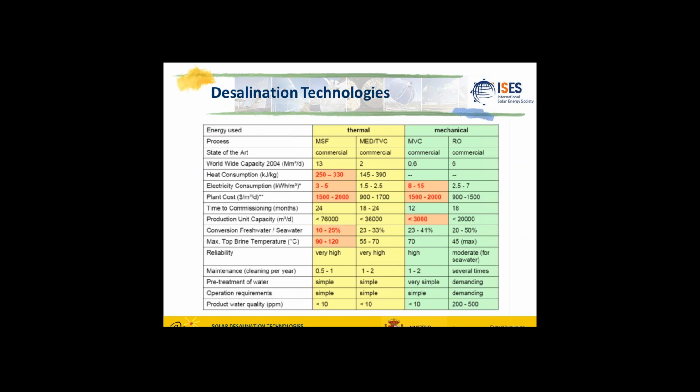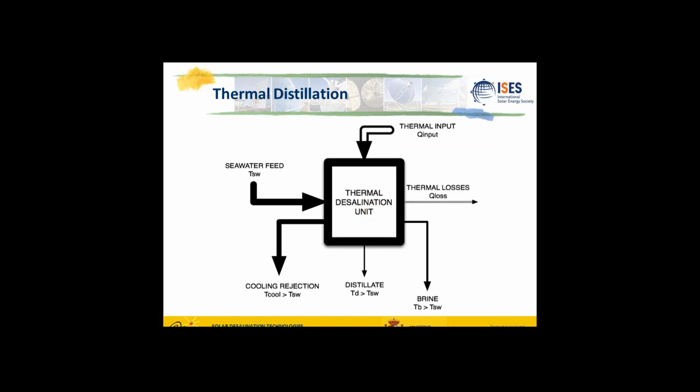In particular, for a typical plant of 50 megawatt electrical, the typical consumption of water is around 6 cubic meters per megawatt hour, which means around 1,600 cubic meters per day. Obviously, the alternative to a wet cooling system in a solar power plant could be dry cooling, but dry cooling implies a 3% higher investment cost for the plant, and also, because the temperature in the condenser is higher than with wet cooling, you are going to lose around 3% of overall plant efficiency.